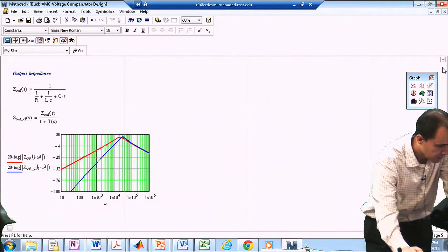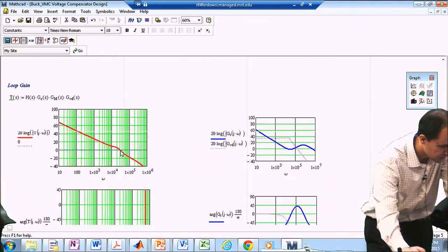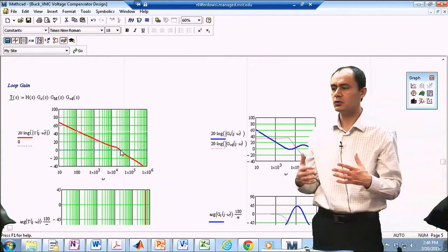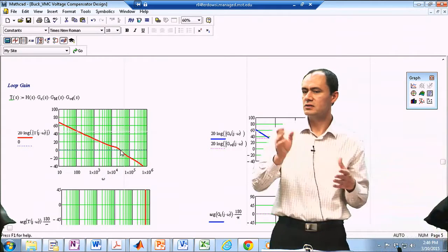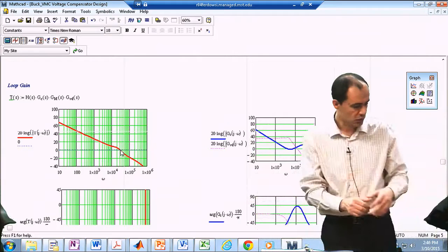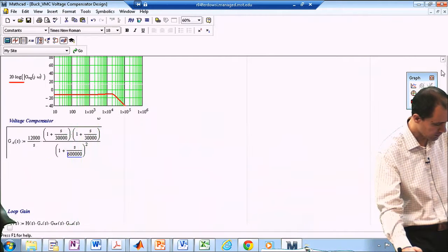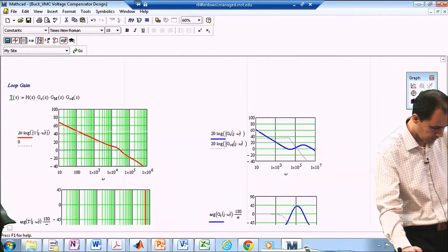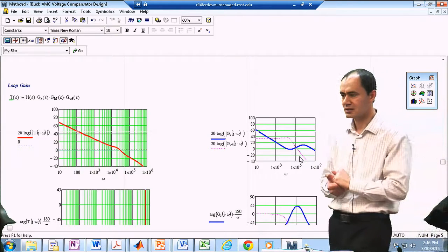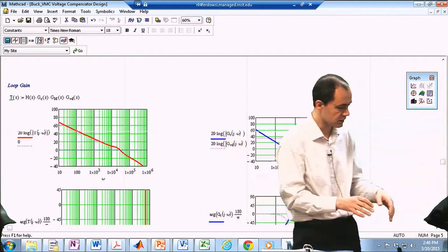If you look at your bandwidth before and after adding the compensation network, there's not a significant extra bandwidth that you're providing. Your bandwidth is kind of limited to your switching frequency, because switching frequency is hovering around 500,000. You need good attenuation at that 500,000. So your bandwidth cannot go beyond this point. Even before, you were almost around that. So if you look at GVD, you are almost in that vicinity anyway. So before and after, the bandwidth doesn't change much. So in terms of your system getting faster, it is not a significant change.